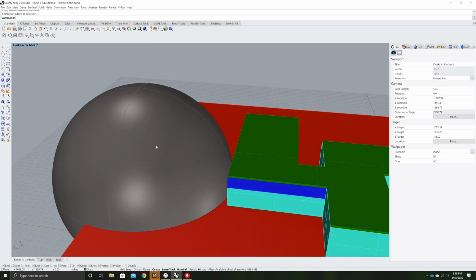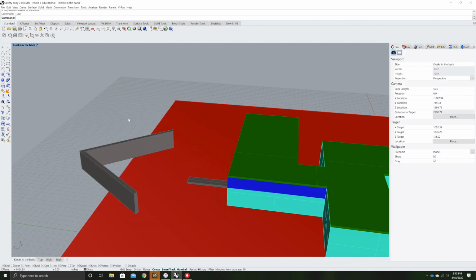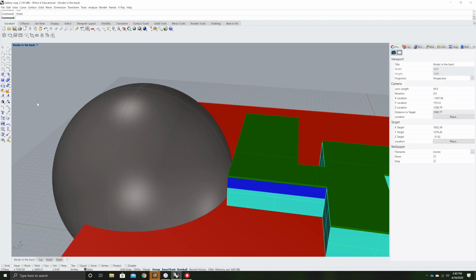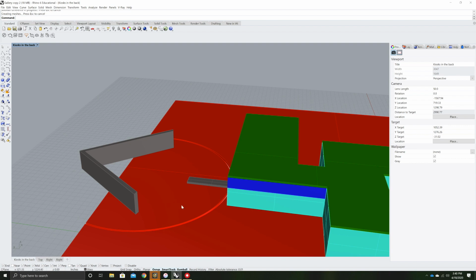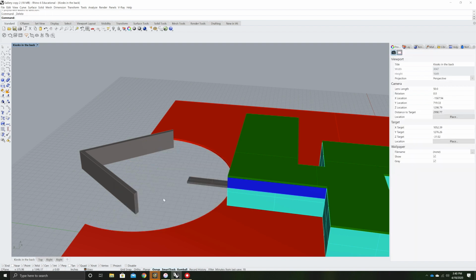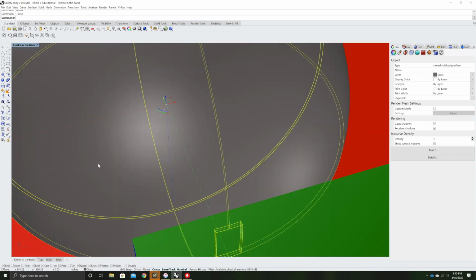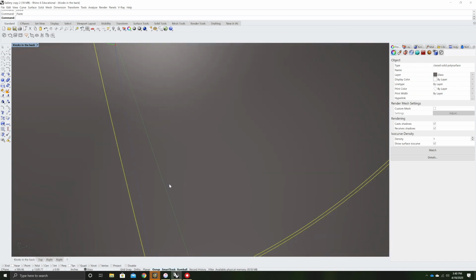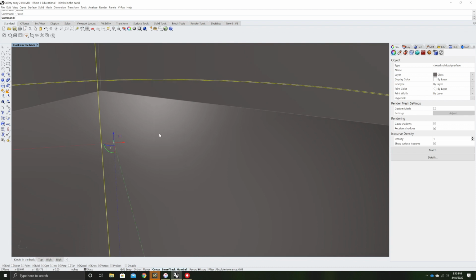Okay. So what I'm going to do here is Boolean difference, but first I'm going to copy and paste, just like you would with a Word document, Control X or Command X to cut, and then Control V or Command V if you have a Mac to paste. And then I'm going to Boolean difference. So click on my floor here, Boolean difference this out, and then it cuts out that whole section there that I can now delete, go Control V, and paste it back in place. All right. The whole goal here is now I want to set a camera, because it is hard to get in and out of this void space I've created.